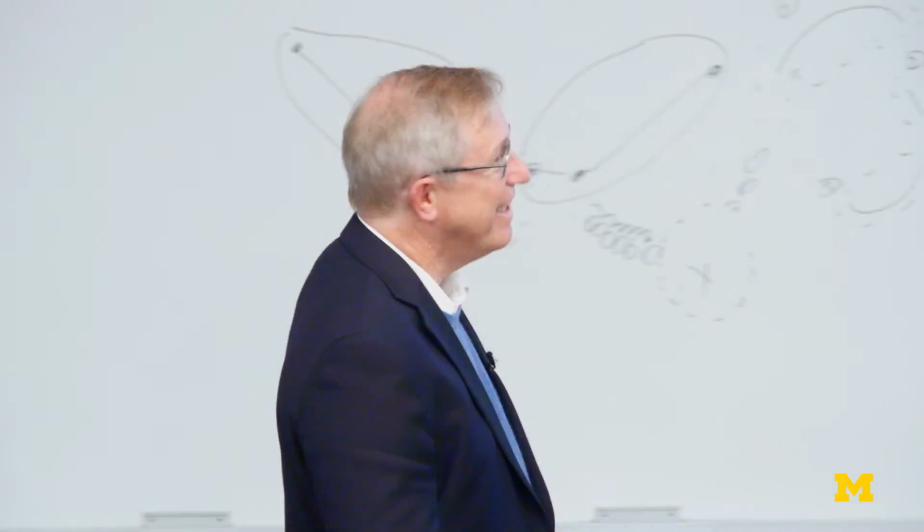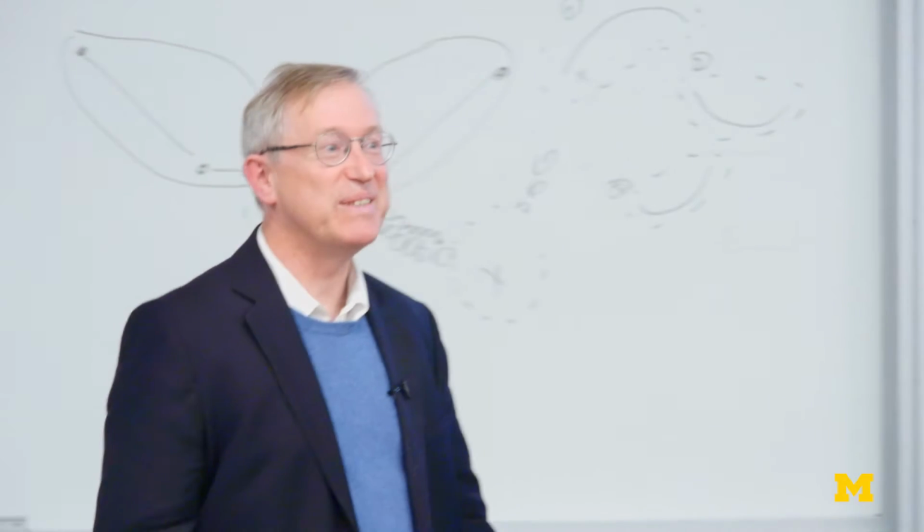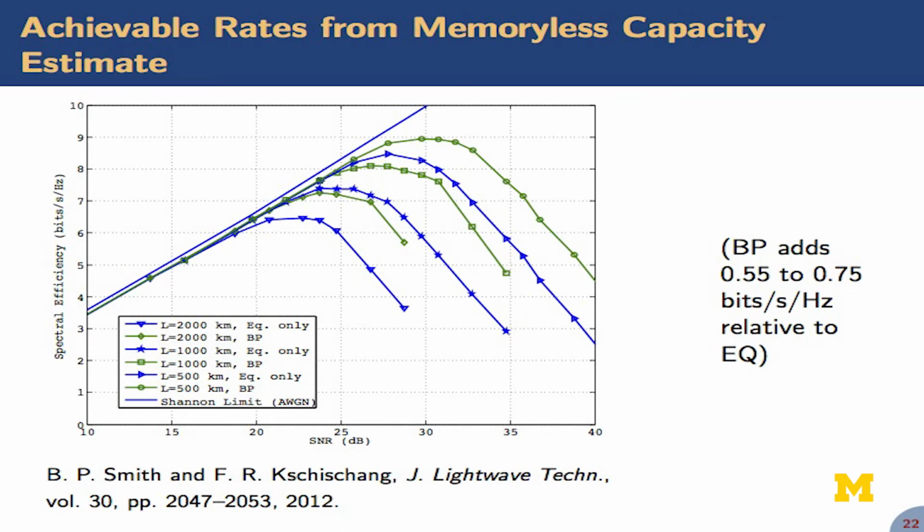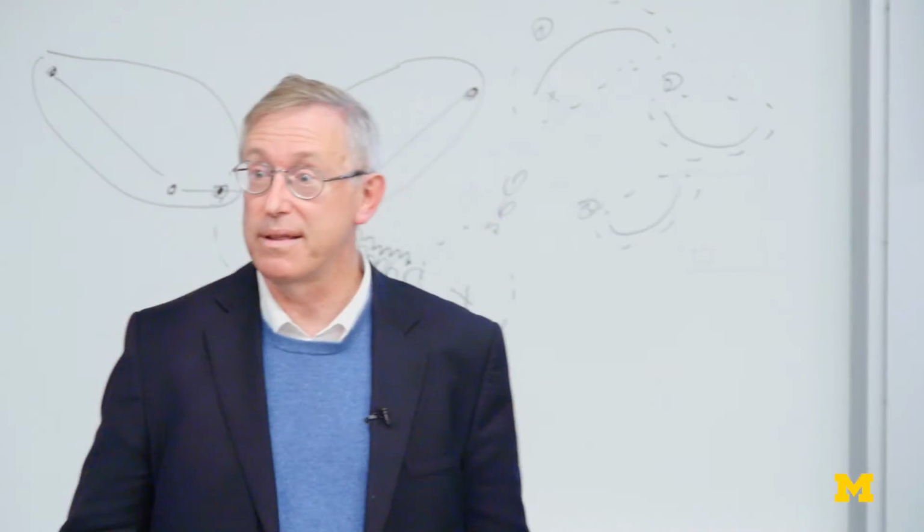All right. So let me walk you through this slide, okay? Because I think it's really, really telling. So this is launch power. The signal gets more energetic as we go to the right. And this is achievable rate. Spectral efficiency I wrote, but it's really some kind of achievable rate. This bound here is the bound that corresponds to the corresponding AWGN channel.